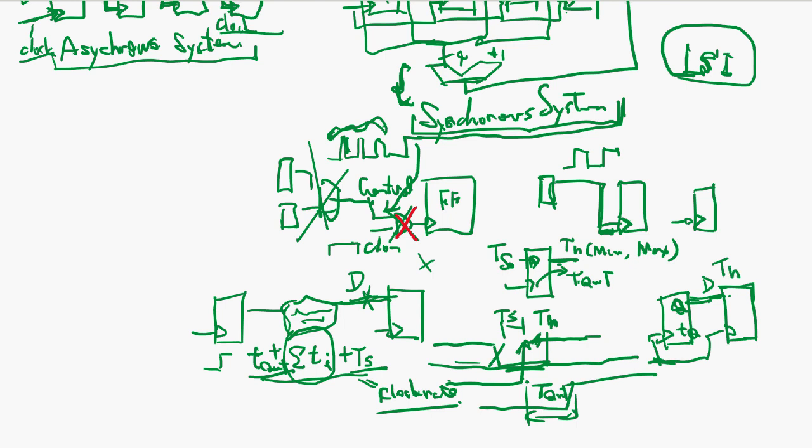You need to hold the data, right? So this whole time, if TQ is too fast, then T hold. You cannot do this because you may get the wrong data into this guy. Most of the time in design, TQ is slower than T hold time.